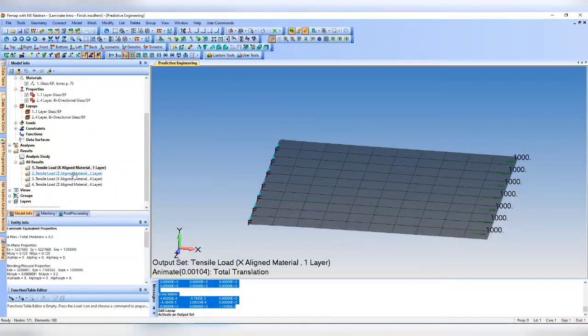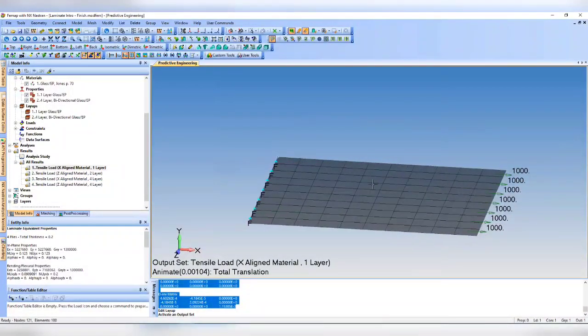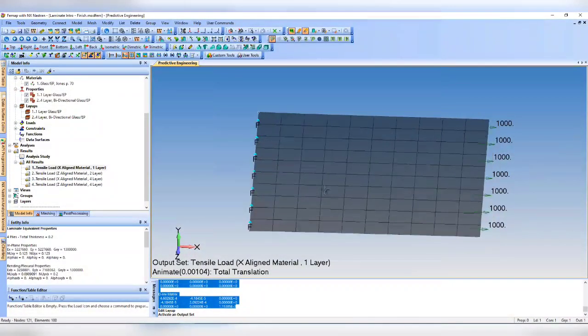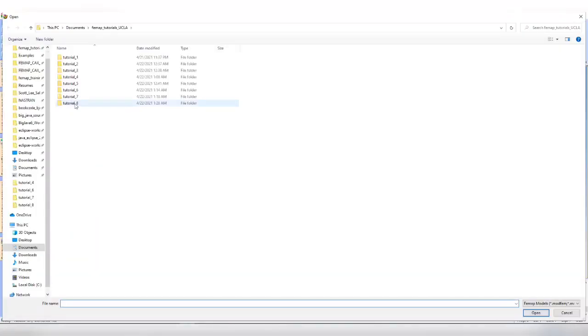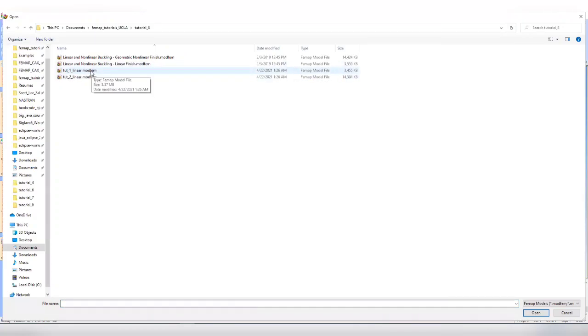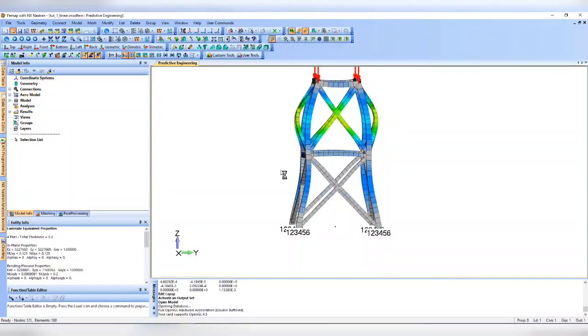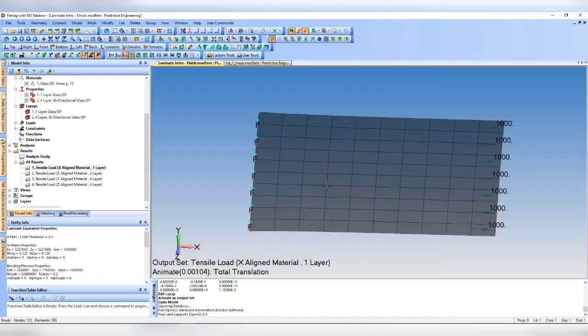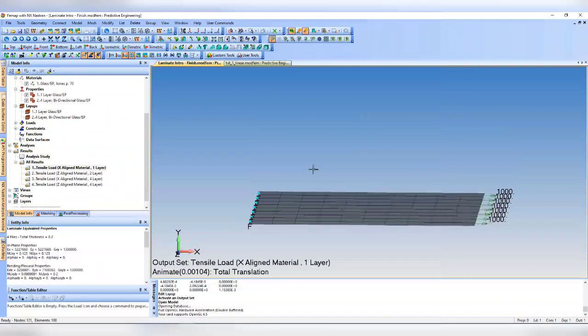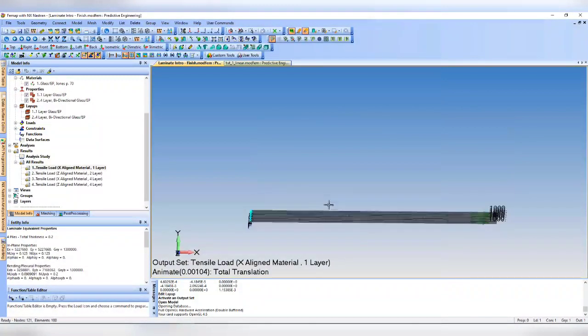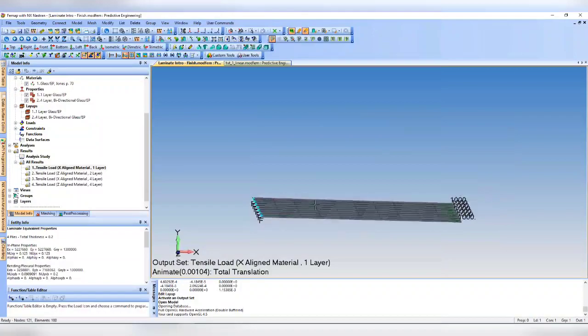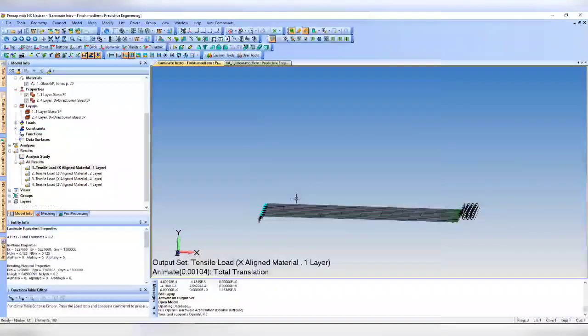All right. Any questions before I move on to the next tutorial, or do you have anything to add, Vinay, to this? I think it's very important to check ply angles. I've seen a lot of designs where that was not done, and it led to some issues in the design process. So it's important to check ply angles, making sure you have the properties measured from test data, that you have a good database so they can have confidence in the modeling techniques. Also, test validation of these models is recommended. Yeah, composites is a different animal, so you've got to treat composites a lot differently than metallics.